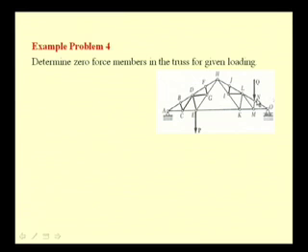But this discussion does not hold valid for this joint N, because we have an external force Q applied at N. Here this element LN and NO are collinear and MN is perpendicular to the same, but since we have this external force Q acting at N, the forces in all these three members are not 0. Now, we have determined that the forces in BC, FG and IJ are 0.